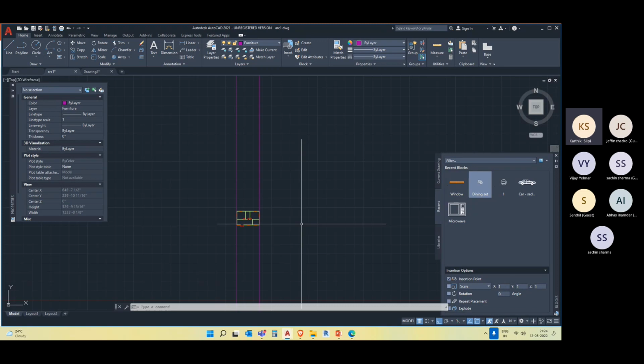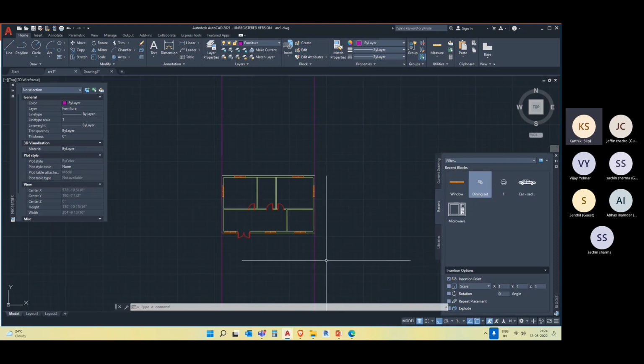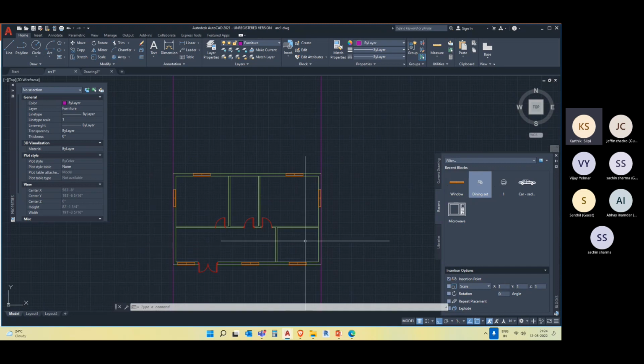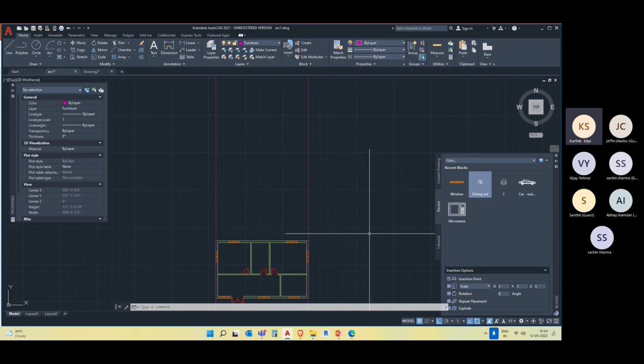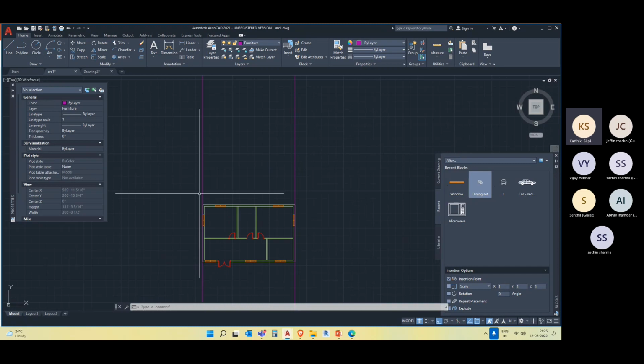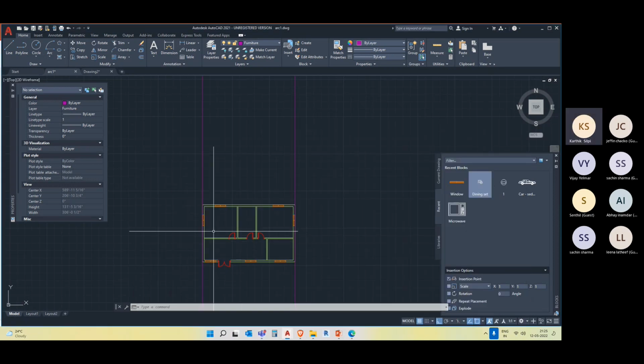Okay. Now after that, why did I draw lines exactly here? Because whatever the front elevation is, that should not be more than this dimension, because this is the start of my building, this is the end of my building. Whatever I draw should be in between the building, this dimension only. So I have taken some construction line so that it acts as a reference and helps me to find my endpoints. I have to complete my building within this point to this point.